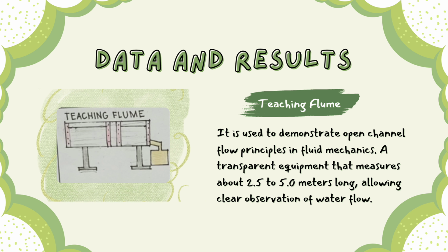It is a transparent, long equipment, usually between 2.5 to 5 meters, that allows us to clearly observe water flow behavior. This device helps us visualize phenomena such as flow rate, turbulence, hydraulic jumps, and surface profiles. It's particularly useful in civil engineering when analyzing river flow or canal designs.